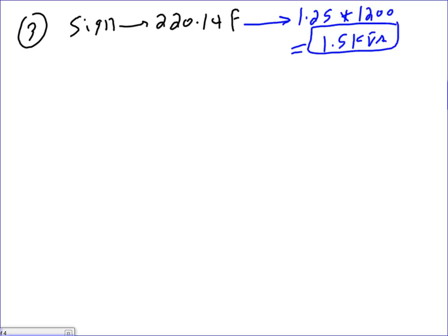Everybody knows when I did the math, I divided by 1,000 without putting it in the formula. I don't want somebody to say, well, how did you come up with 1.25? It's 1500 volt-amps. My answer's in the K. When you get into the commercial, guys, your answer's in the K. You have to be working in kVA. A volt-amp by itself is meaningless in a commercial building. So it's 1.5 kVA for the sign.